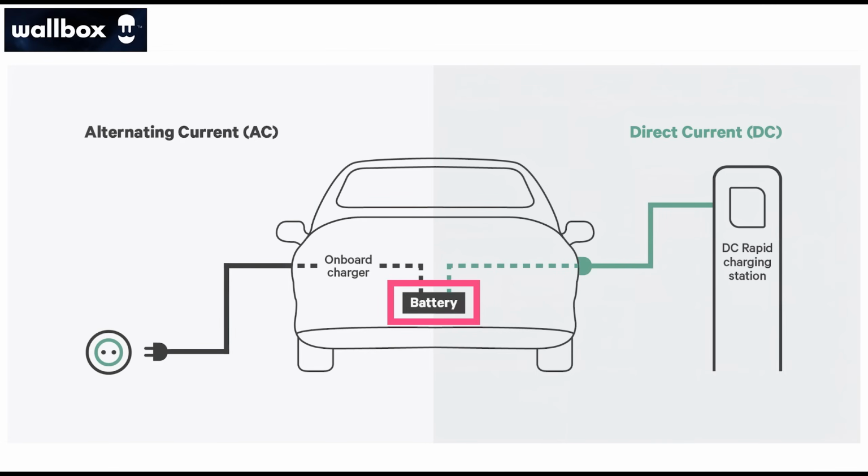So then how do we determine the charging curve? Well, we need to think about what limits the power in the battery. Okay. And so those limits come from different sources. One might be a thermal limit. We don't want to get the battery too hot. So if it's a super hot day, we're in a hot country, and the battery is generating a lot of heat, maybe because its internal resistance is a bit higher or whatever, which could be for lots of reasons, then the charging power might need to be limited to avoid overheating. Maybe the cooling system in the battery, which would normally keep it cooler on a hot day while you're charging, is struggling. But having said that, in general, warming the battery up helps with getting more power in.